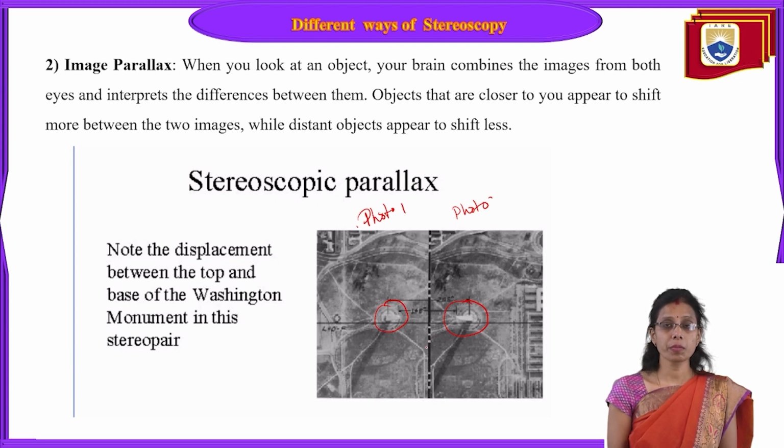Relief displacement means that when the flight line goes in a direction, you will find that a building or an object in the image is displaced a little bit. Like in this image, you can see a little side view. But in this image, you see this tower is visible from here to here. The base is visible and this much portion is visible. So this much portion is displaced in this photo and this much portion is displaced in this photo.